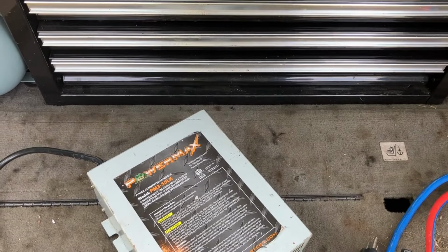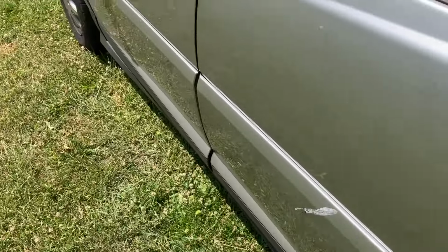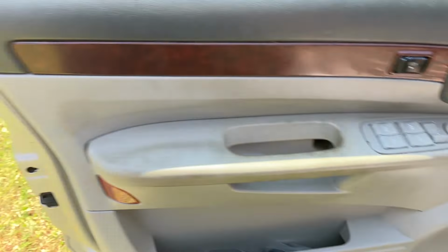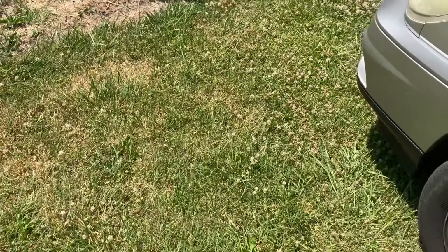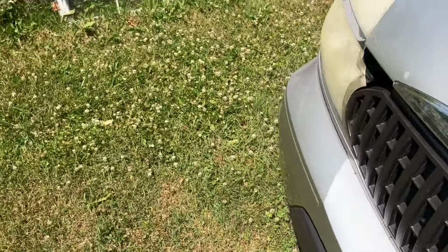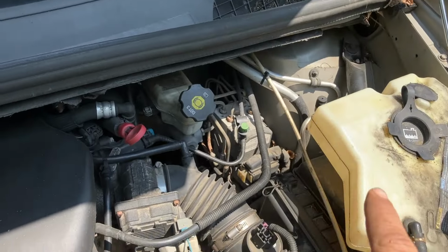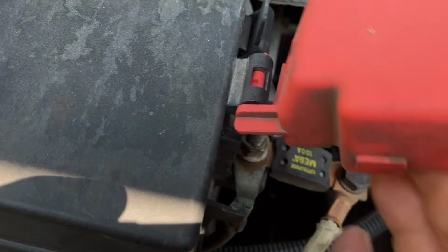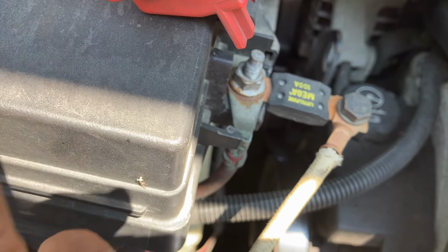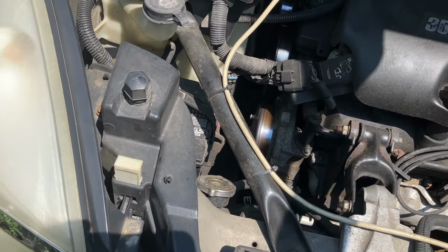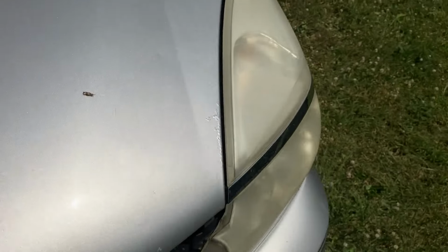So it's really pulling that inverter, and then that inverter actually runs, I have the ground side of it hooked into the chassis of the car, but the positive actually runs up here. It runs through this white wire, comes through the firewall, runs through this white wire, and goes to that fuse. And it works. It doesn't blow any fuses or anything. So it must draw less than 100 amps.